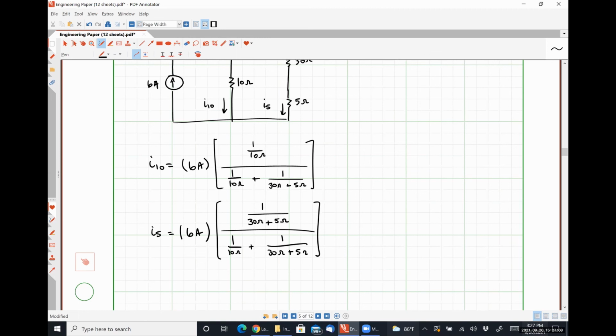All right, so that has been source combination. Just to recap, voltage sources in series can be combined. If they have the same polarity, they add together. If they have opposite polarities, there's subtraction involved. Current sources in parallel can be combined. If they have the same direction, they add together. If they're of opposite directions, subtraction is involved.